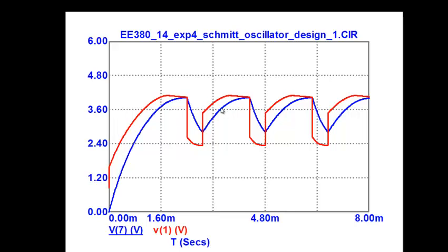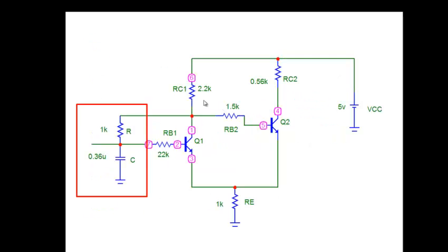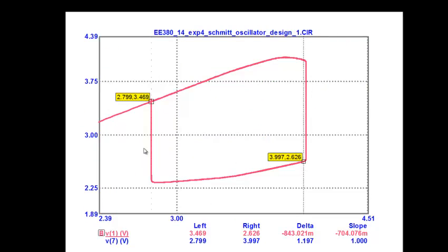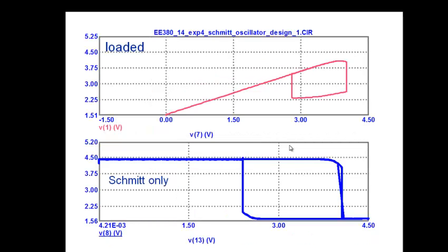So now the issue was, what is happening here? Yeah, we managed to get oscillation. So, there is a Schmitt trigger here. You can still take V0 here and Vi here, the input here, and you can plot the Schmitt trigger characteristics by plotting V0 against Vi. So when you plot the Schmitt trigger characteristics, note what has happened to the Schmitt trigger. Let me plot both of them together. Forget about this initial part. This is my Schmitt trigger.